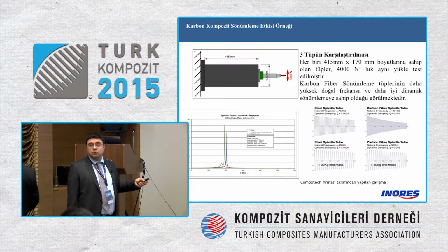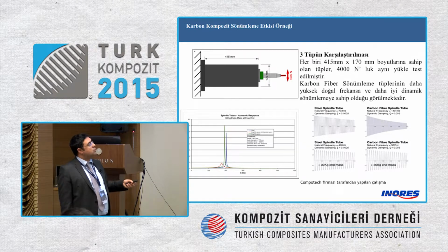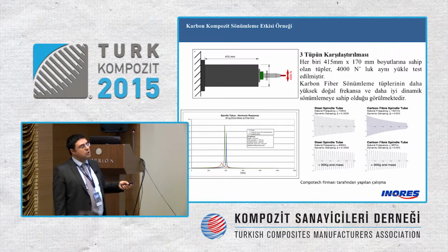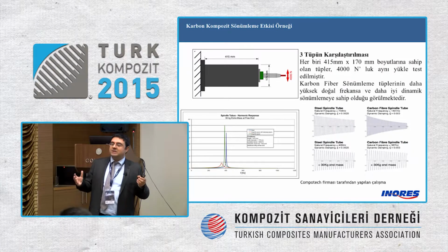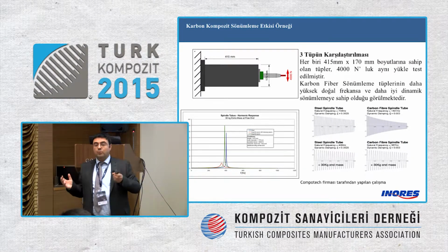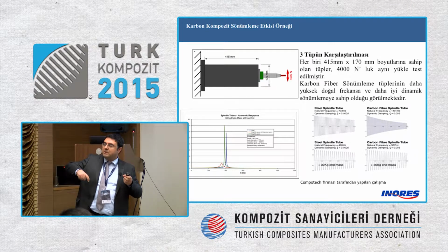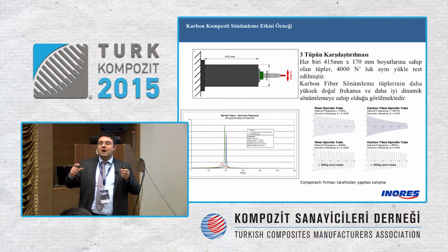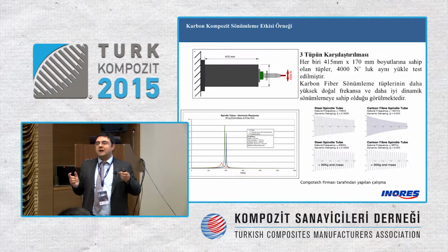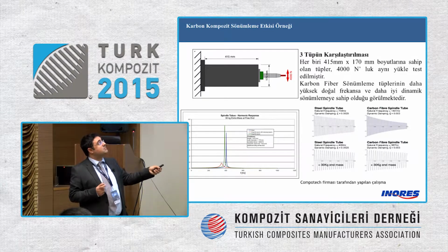Similarly, when there is a load on it, what is the situation? If there is a load on the tip of it, what happens? The natural frequencies do not change very much. Carbon fiber decreases from 500 to 300. There is dead weight over here, and the steel has more dead weight than composite material. And of course, when you put an additional weight on the composite, the impact is a lot different.